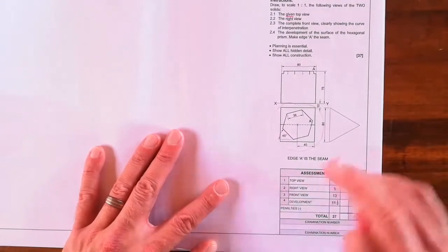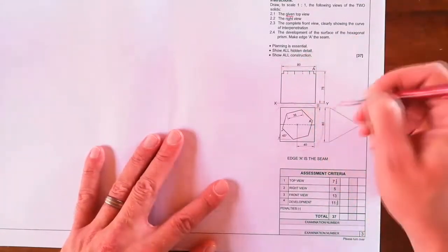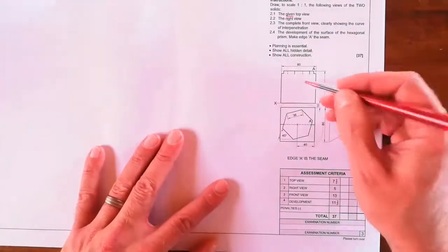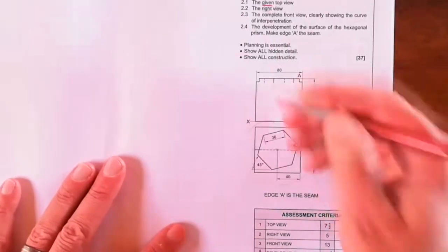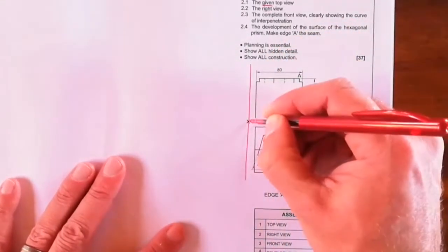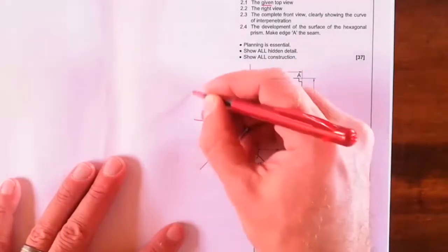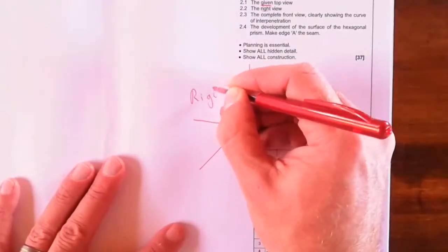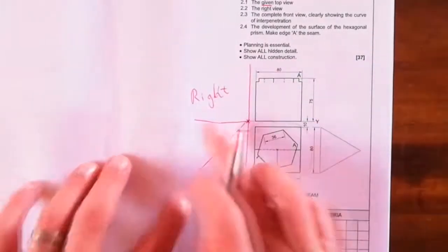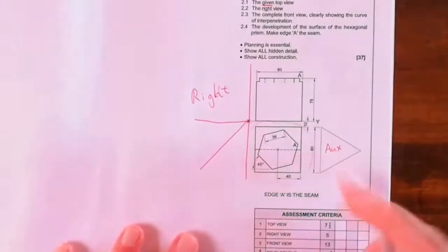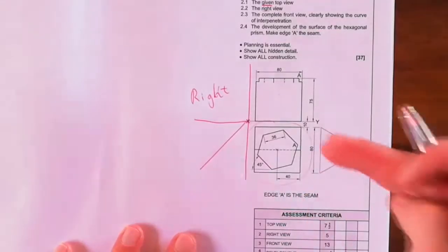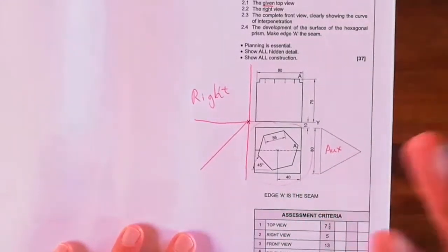The right view, of course, here it's going to be important to remember your first angle of the graphic projection. If they've given you the front view and the top view, then your right view is going to be on this end, right? Okay, so your placement is going to be important. That is an auxiliary view. Remember that, okay? And then you grade 12, but they can use elements that you learned in grade 10.